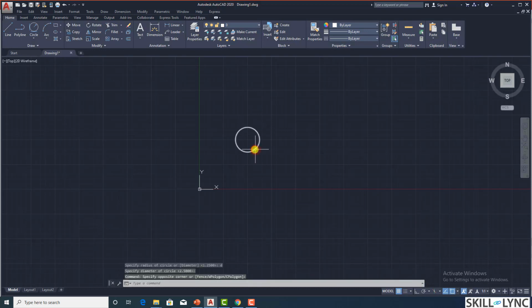Alternatively, if you don't want to invoke the previous command but rather enter it yourself, go into the dimension command and type in 2.5. You're free to use whichever you want. But if you're doing a replicated task, you can always press enter to take in the previous entry. So this sums up the first method of drawing a circle, that is by specifying the center point and then specifying either the radius or the diameter. By default, the command is radius.